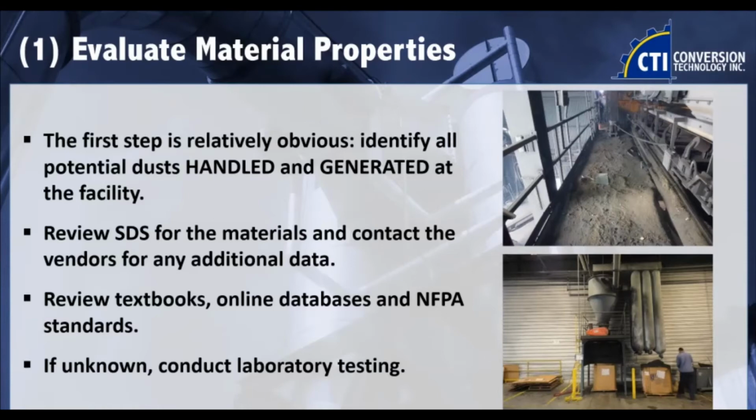So you need to know, well, what do I include in my DHA? Like I said, you can use every inch of your process and equipment, but are you going to want to put in suppression systems and increased dust collection if you're moving salt around? No, salt's not a combustible dust. So knowing which materials that you handle and generate or otherwise use is pretty important.